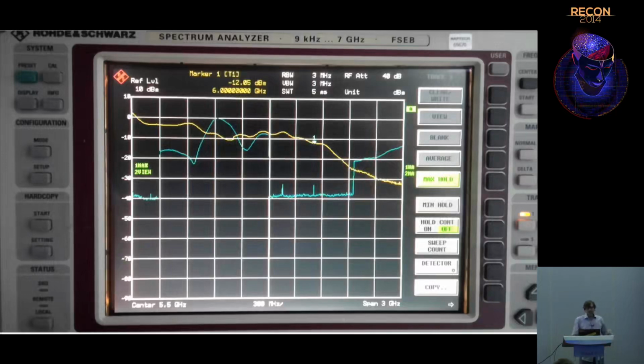And so it's the fact that I'm pushing the limits of the amplifier that we get these crazy curves and peaks. But it shows you that by using a dirty trick like exploiting the harmonics of the IF, we could actually do things potentially useful up around 7 gigahertz that we wouldn't be able to do by configuring it in the traditional way.